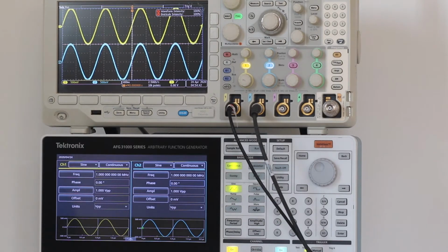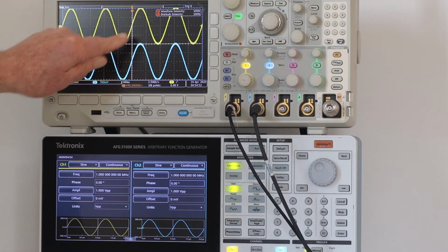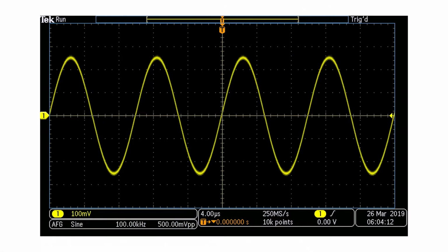As you can see by looking at the sine wave, the rate of change is greatest when the voltage is least, as the trace crosses the x-axis, and the rate of change is least when the voltage is greatest, at the positive and negative peaks. That is the way a sine wave works, and it is a consequence of the rotary nature of the generator. Now let's look at some phase relations.